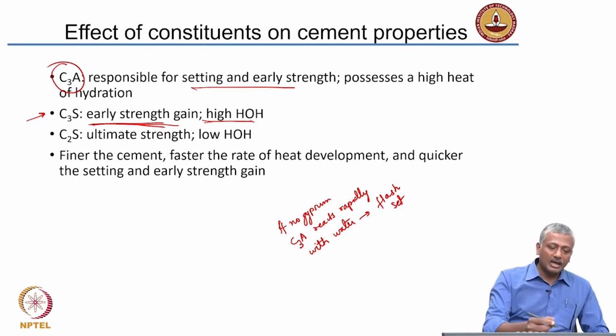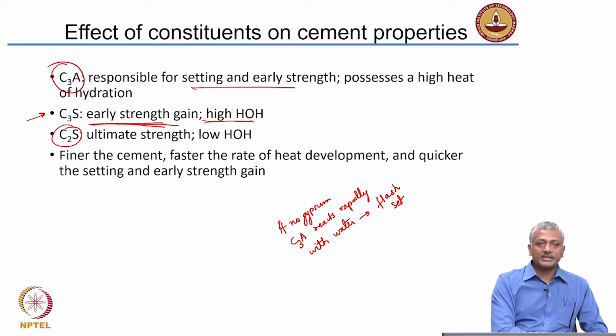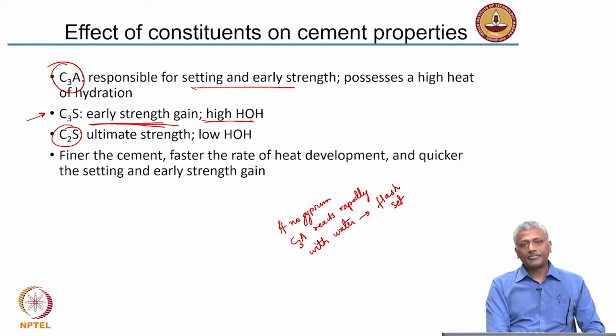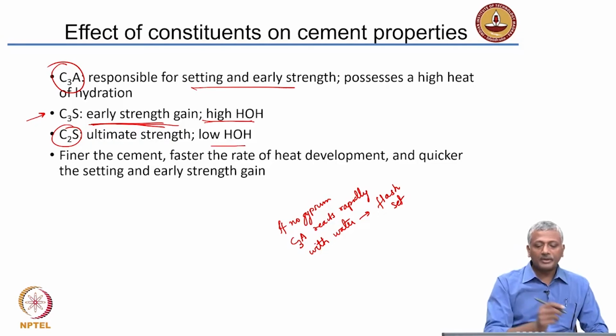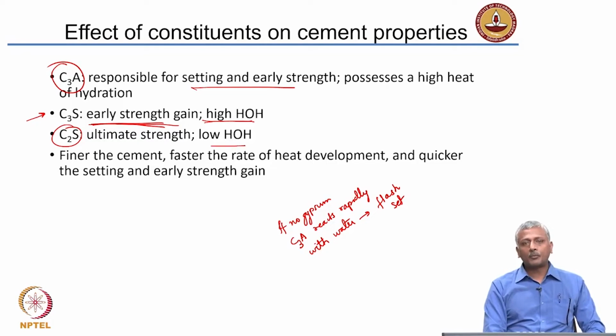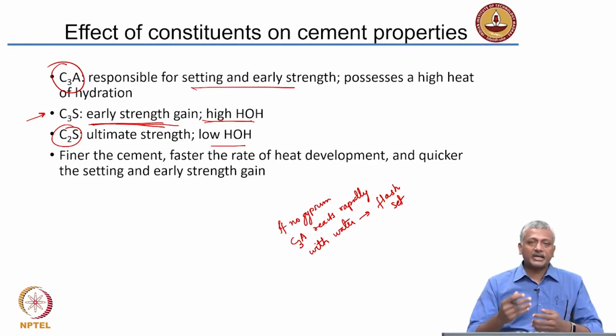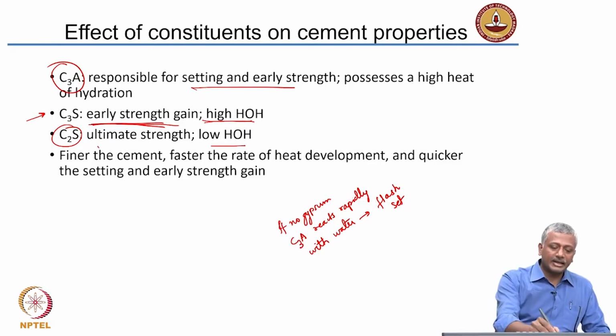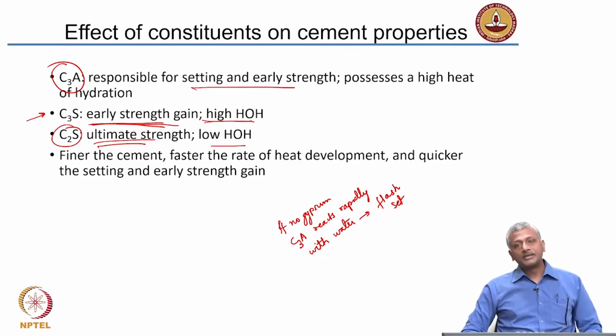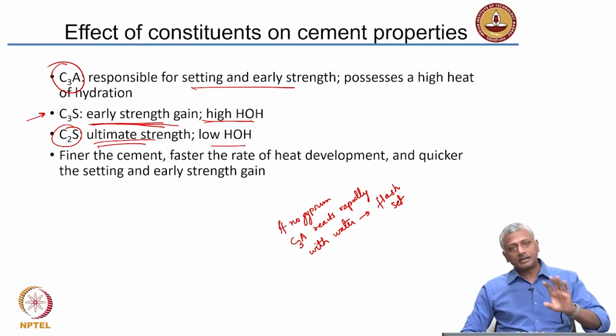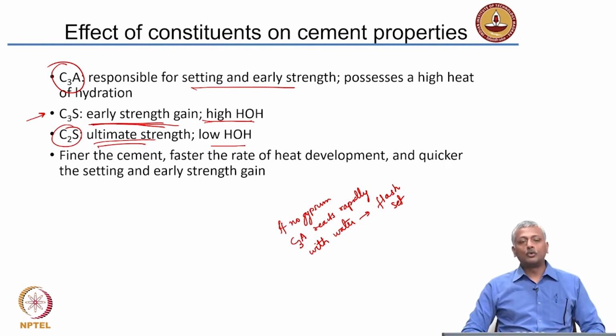On the other hand, when you have a cement which is rich in C2S, dicalcium silicate, it is very slowly reacting and it has a low heat of hydration. So, it will possibly not even react in the first few days of cement coming in contact with water. So, your C2S reaction may actually start very late and it is actually responsible for the long term strength of your concrete. So, it will slowly be reacting. As long as there is water available, it will continue to react and then provide strength over the long term.